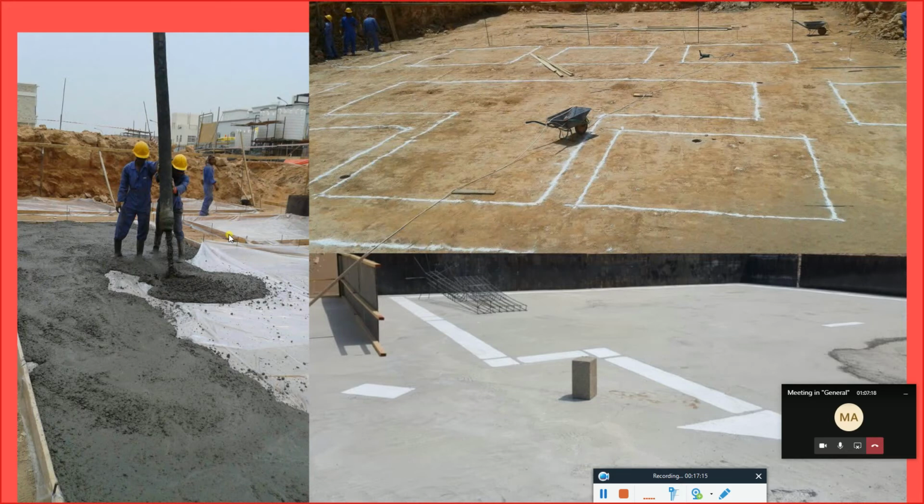We normally have the formwork. So this is the formwork of the foundation. Normally the depth of the BCC is a fixed value, which is 100 mm. So you can see that the BCC for all these foundations is 100 mm. And if your foundation, for example, is 2 meters, then normally we have 100 millimeter extra from this side, 100 millimeter extra from the other side.